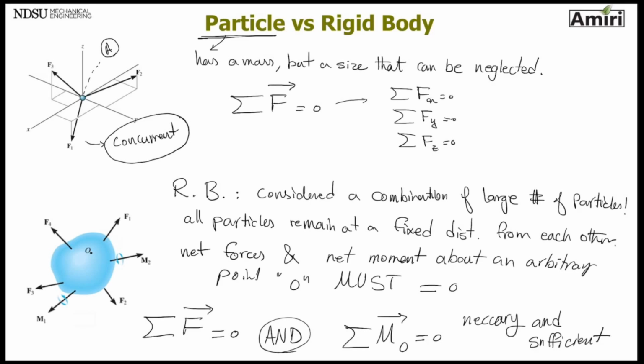Okay, so this rigid body that I have, which I want you to remember, is a 3D rigid body. It's a potato, right? It's subject to some forces, F1 through F4, and two couple moments. And how do I know these are moments? By looking at these little arrows that they put, which show the direction of rotation.